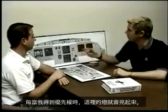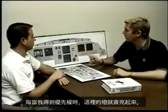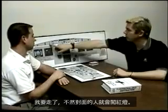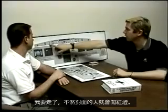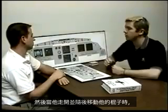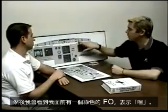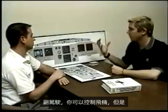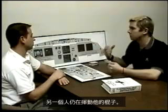As far as the lights go up here, whenever I get priority, the guy on the other side is going to get a red light. And then if he subsequently moved his stick, I would see a green FO in front of me indicating, hey, first officer, you have control of the aircraft, but the other guy is still moving his stick.